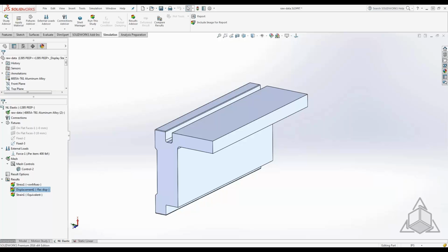So obviously the thickness of your part will play a huge part in terms of how it will deform. Now with that said, you are getting much closer to actual results if you are getting raw data from your tensile stress machine and using it on similar geometry. So it doesn't have to be exact geometry.